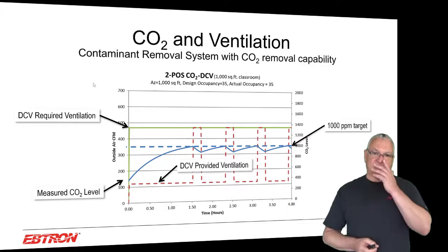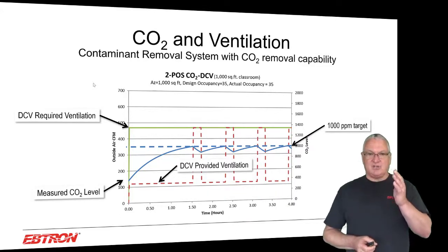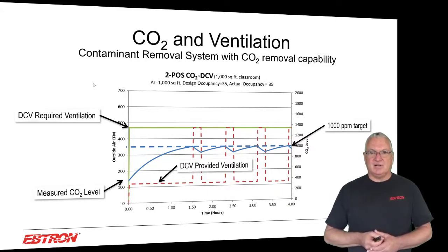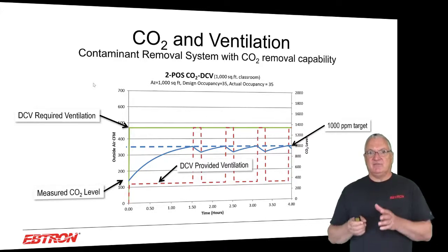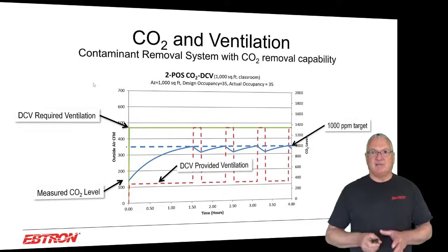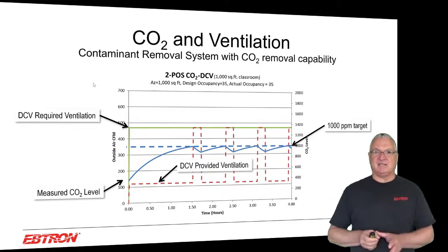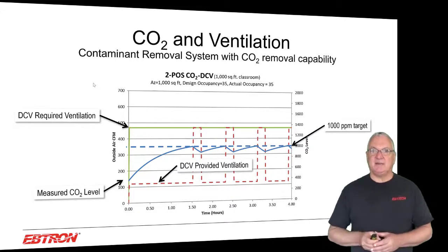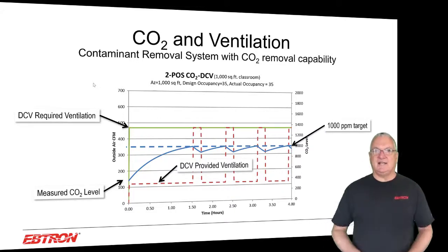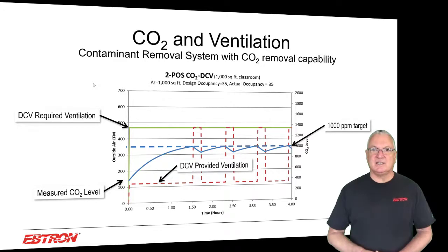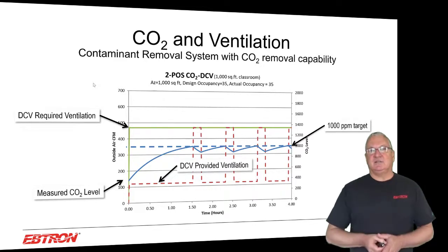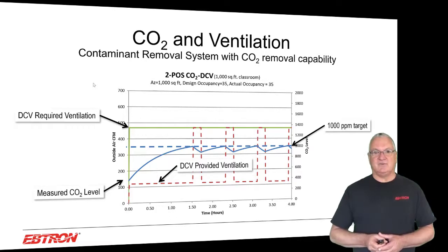So what I have here is a system that has filtration that actually effectively removes some of the CO2. And I can imagine people that don't understand the relationship between CO2 and ventilation, that think CO2 is a contaminant, saying, wow, what a great idea. I'm going to put this in, I'm going to lower the CO2 levels, and now I'm going to simultaneously do CO2 demand control ventilation.